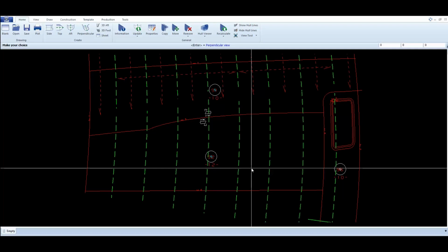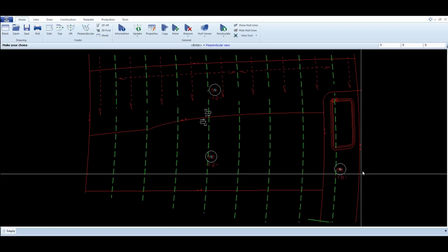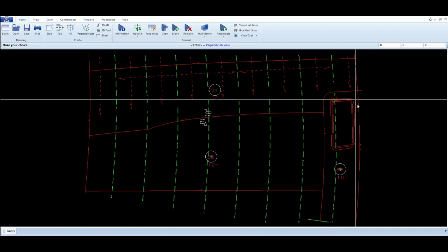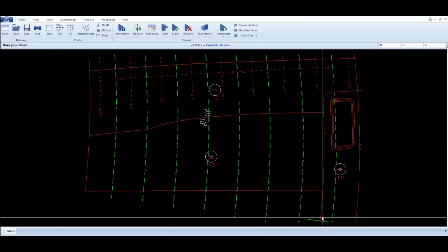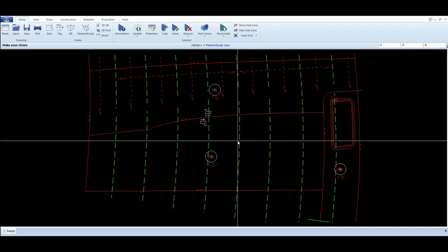Now, we have a view where we only see the relevant information for us. So as little information as possible, but the complete information of what we needed. So we needed to see the two shell plates because we want to calculate jig pillar heights for these two plates. These two plates are completely visible in the view. We also see a part of this shell plate because it is until here, until the edge of the shell plate. So part of it is visible, but you see it is not completely visible. What you also see is that this view is a regular view. The construction elements are also visible, but we have as little information as possible that is relevant to what we need.